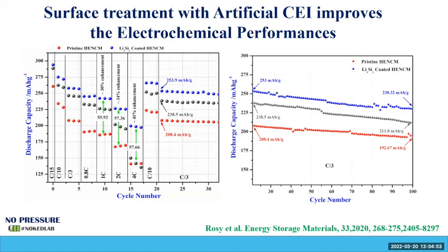I understand that you had a better technique, but how do you explain the higher capacity of the coating? Okay, so this is a very good question. We get it regularly. One thing is that all these materials are highly unstable even at room temperature. And you know that the processing of the battery involves exposure to NMP, methylpyrrolidone. We can see that it is reacting spontaneously with any organic solution you put in. So you start less good with the oxide material when it is not coated. So the coating improves the capacity even at the beginning.